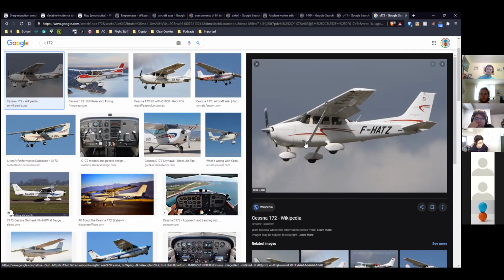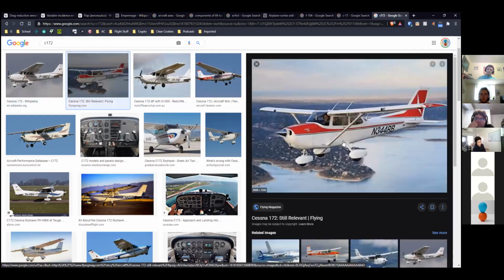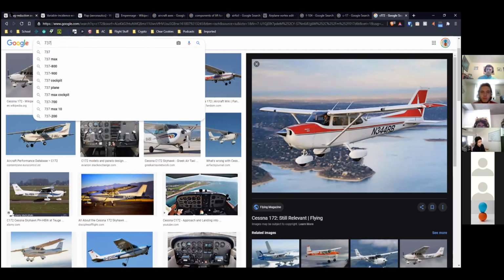And so they put a really little simple fillet in there to reduce that, even though it's probably not that big of a difference. It still helps and it's really cheap. So they don't have one here because you see that window there, that window is attached to the door. So they can't fit one in there, but every airliner ever, their root fillets are basically built into the wing.